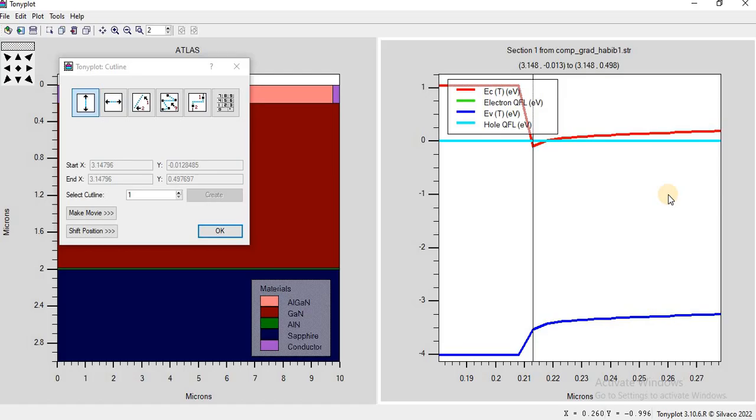So a two-dimensional electron gas occurs when electrons are confined to an interface between these two materials. These electrons can move quickly without colliding with any impurities and from which they cannot escape. The effect of this is the creation of a very thin layer of highly mobile conducting electrons with very high concentration, giving the channel very low resistivity, or to put it another way, high electron mobility.